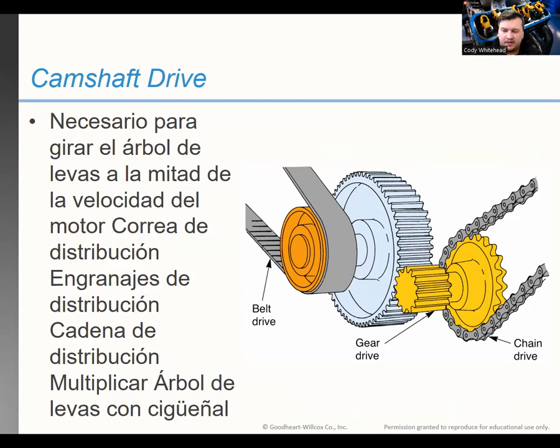So to do all of that, we have timing belts, timing gears, timing chains, that time the camshaft with the crankshaft. There are different ways: we can have chains that run the two, or a belt that runs the two together. Some engines out there, Audi, Volkswagens, and if you ever work on some old Ferraris, I think the old Enzos are like this, had a series of gears that looked like a bunch of clockwork to time it all together as well, but that's not very common.